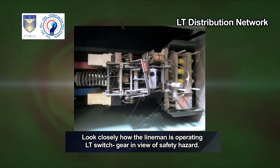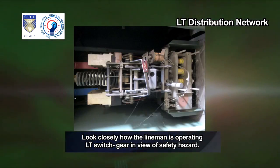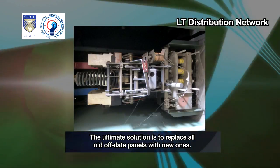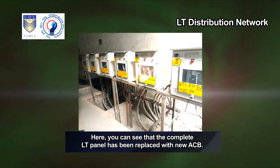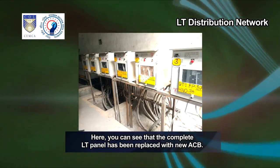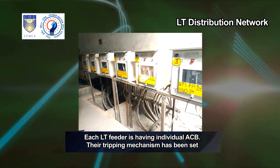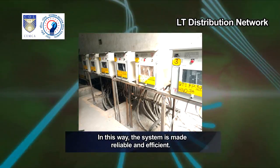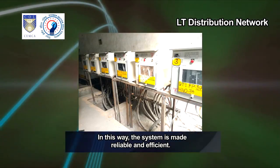Look closely now. The lineman is operating LT switchgear in view of safety hazard. The ultimate solution is to replace all old off-date panels with new ones. Here you can see that the complete LT panel has been replaced with new ACB. Each LT feeder is having individual ACB. Their tripping mechanism has been set according to their load profile. In this way, the system is made reliable and efficient.